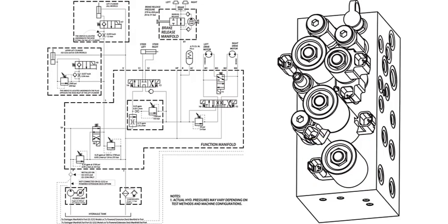The following pages will utilize the schematic and manifold to outline, functionally, what happens when each function is selected. This page is designed to show a basic flow path for oil when the electric motor runs. This condition only exists for a moment under normal operation, before a directional valve is shifted to redirect the oil flow to the actuator for the function selected.